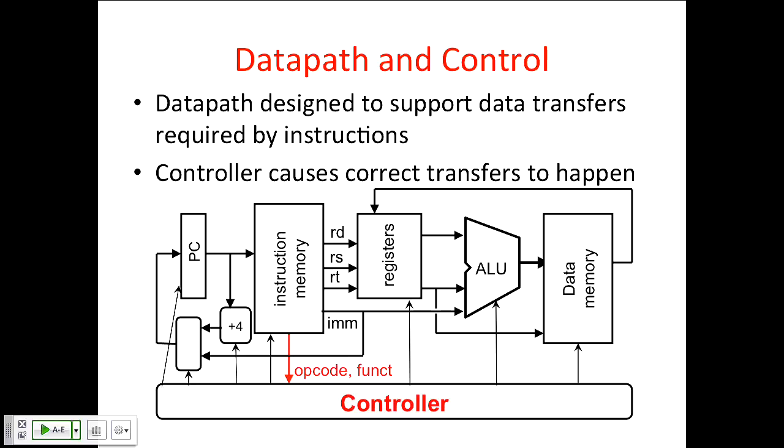What's interesting is a lot of CPU designers always get excited about building the data path because, how fast can I make an add or a floating point multiplier, or how small, or how low power can I make those pieces? They're kind of fun to design. But what you find out in doing a lot of CPU design is, this is the bulk of the logic gates, and this is a tiny fraction of the logic gates. This is fun to design. This is really hard to design. So all the bugs are in the control logic because it's where all the complexity is.